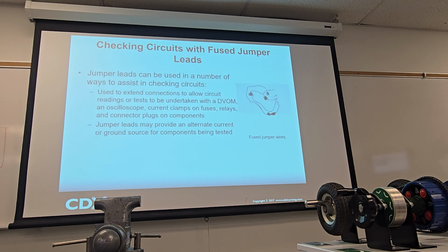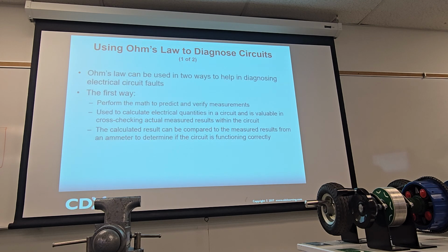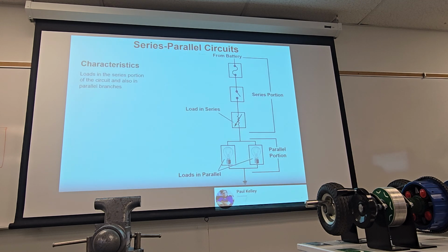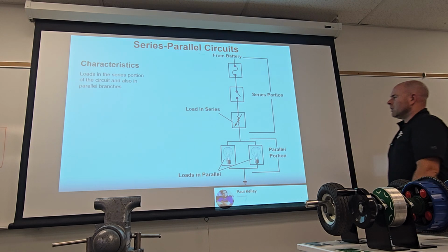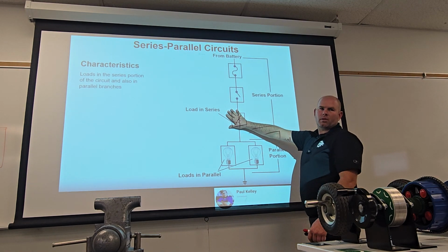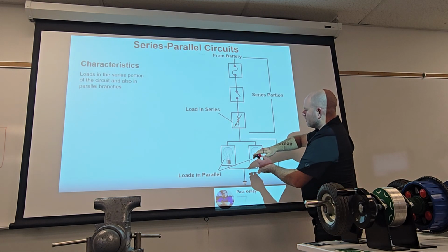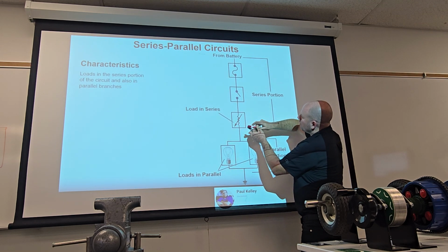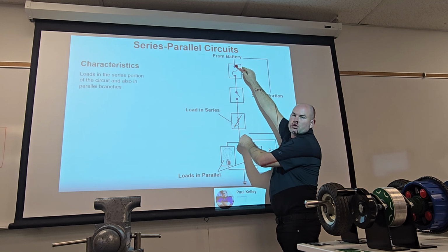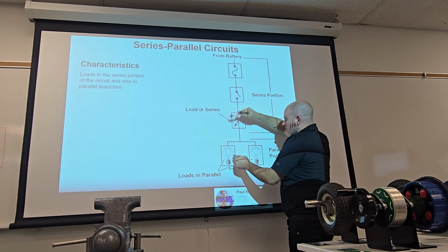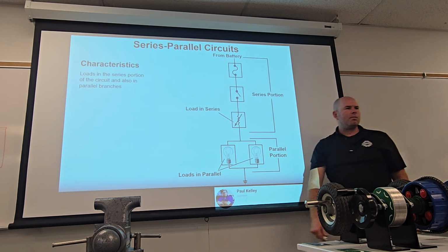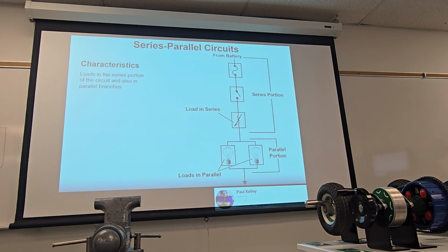What that means is, if we were to do the voltage drop, let's see if you can follow what I'm saying. We'll go with this one. Although, do me a favor and kind of ignore this. Let's just pretend it was just a parallel. If I do a voltage drop right here, and let's say I drop 0, and I do a voltage drop down here, and let's say I drop 12, what side's the problem on? You don't know. I do.